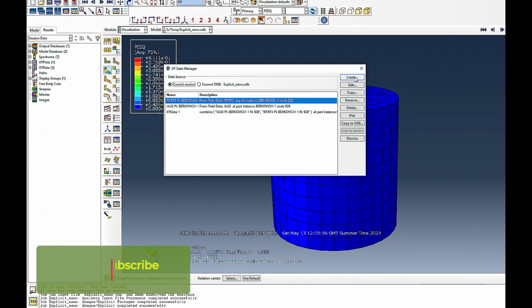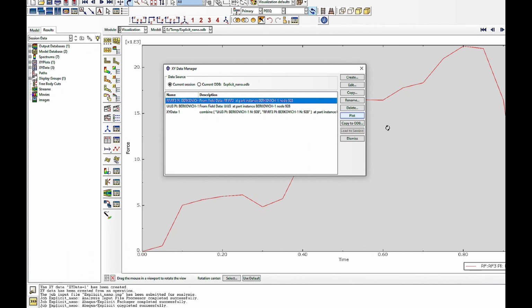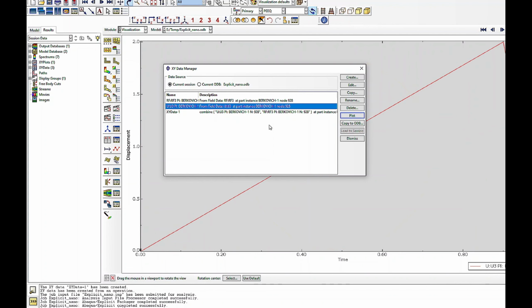And now if you plot this, you will see slight differences because it's elastic plastic loading. These oscillations are coming from the mesh because your mesh is starting to distort and struggle, so these could be numerical errors as well. While this should be a straight line, as you can see, load and unload, because we are applying a displacement